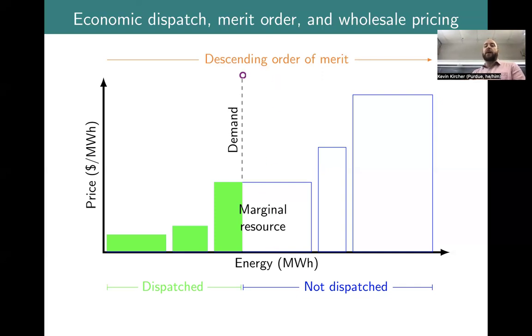So yes, and that's one reason why we see deviations from the merit order, this idealized ranking of least to highest cost resources. When you submit an offer, you might say I must run for at least 8 hours or at least 4 days or whatever it might be. Those enter as constraints in this optimization problem, and they affect the way that plants are dispatched. So this merit order view is stylized, and real power systems don't work exactly this way. It's a first order heuristic for understanding what we're trying to do, and then understanding deviations away from that that lead to higher cost systems.